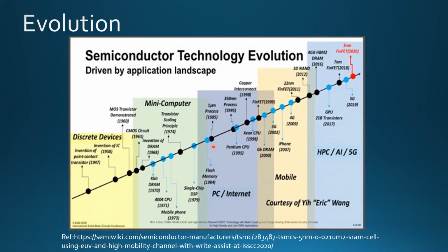Some of these nodes were commonly used, like 180 nanometers and 110 nanometers, especially for sensor based applications where speed is not a criterion but accuracy is. The 5 nanometer technology is mostly digital driven, where speed is mainly the selling point. As technology shrinks, the channel length of the device reduces, and thus we can incorporate more circuits in an IC, and the speed also increases.